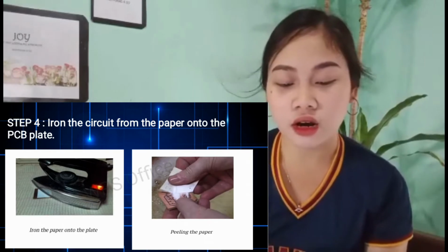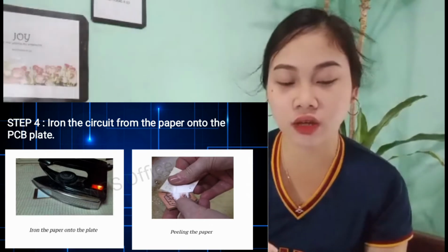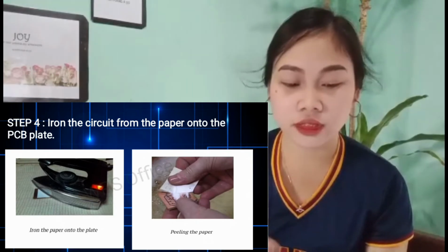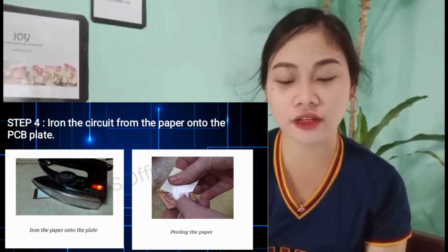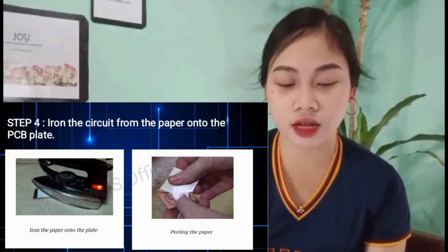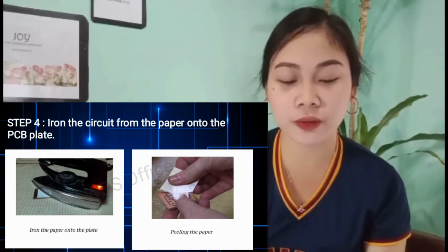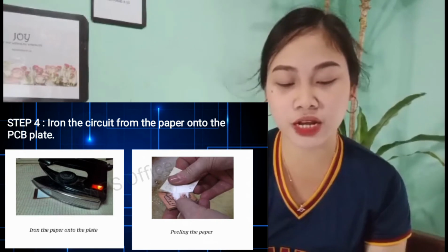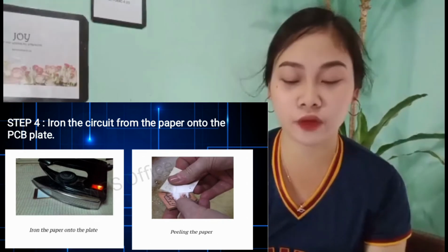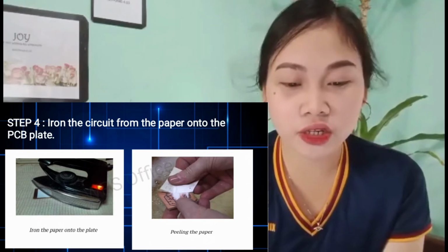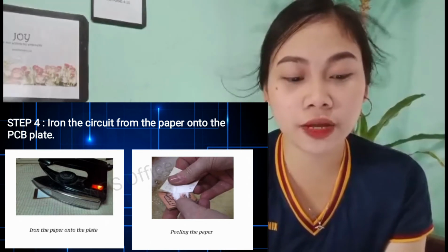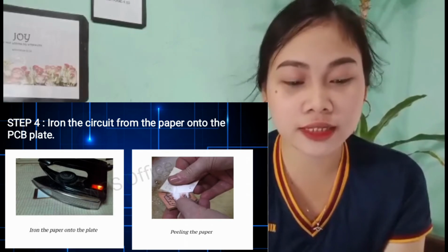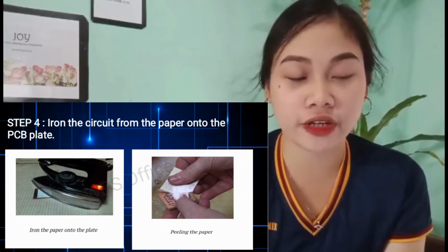Using pliers or a spatula, hold one end and keep it steady. Then put the hot iron on the other end for about 10 seconds. Now iron the photo paper all along using the tip while applying a little pressure for about 5 to 15 minutes. Pay attention to the edge of the board. You need to apply pressure and do the ironing slowly. A slow, hard press seems to work better than moving the iron around.